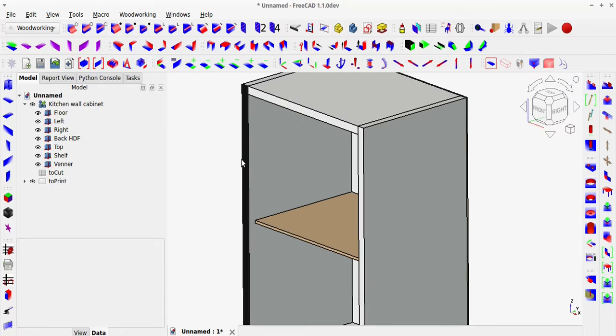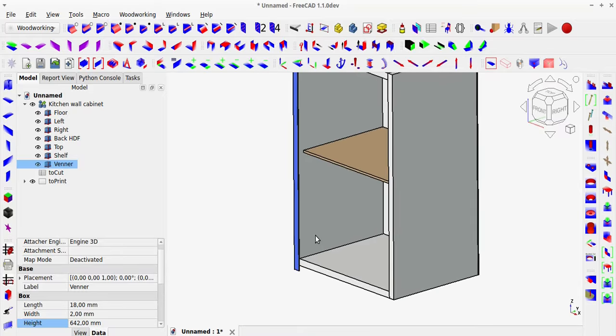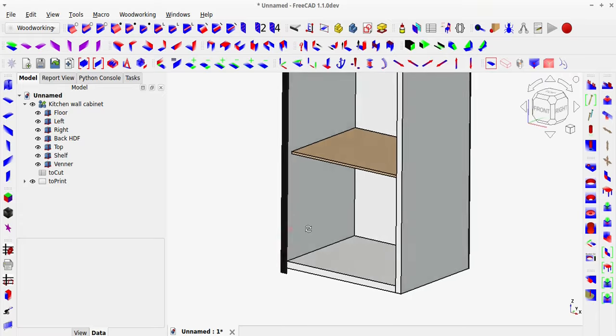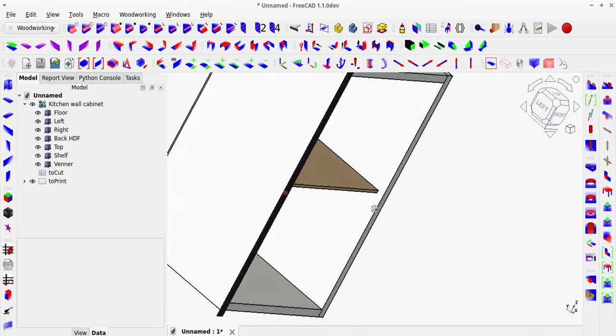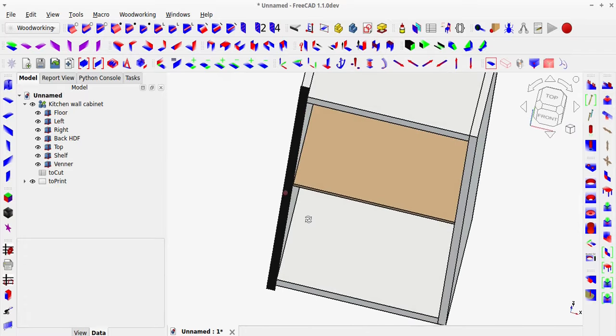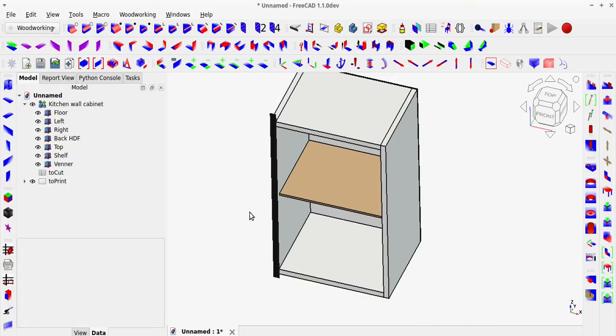You can modify the length and width and thickness and other parameters of the applied veneer, meaning you can more accurately calculate how much veneer is needed and what spacing should be maintained when calculating board sizes. In practice, adding veneer to an edge always requires slightly more veneer than the length of the given edge. Because the veneer is a separate object, you can increase its length, thus simulating the amount of veneer needed.